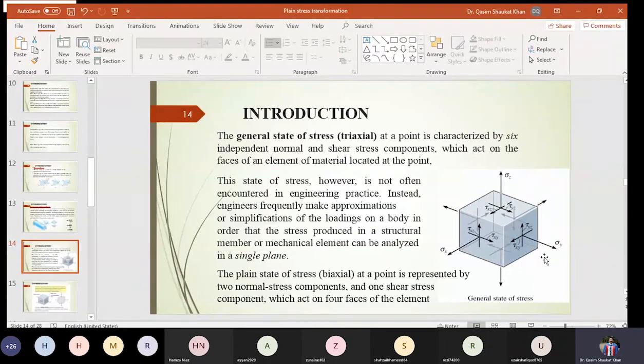Triaxial stress. So now the point to be noted, let's say first I am just focusing on this plane, which is towards the x-axis. Now we are just seeing that there is a stress which is acting along the x-axis. So this stress is your normal stress, which will result in either tensile stress or compressive stress.